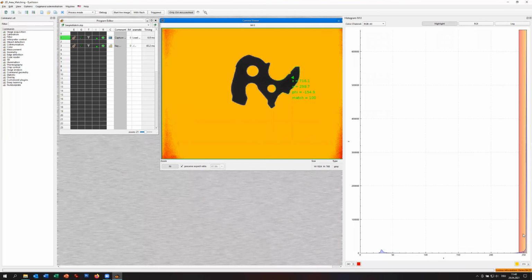If you have a real line scan camera, the illumination could only change from the left and from the right, but never in the corners of the image, because the image is generated line by line while the part is moving through.